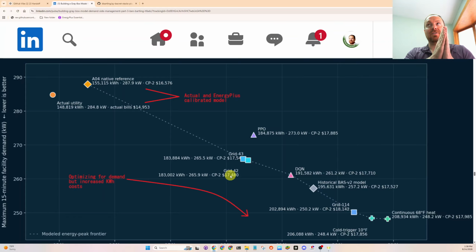do a series of setbacks. So 60-minute pre-start, 180-minute pre-start, even longer than that. And then it also has the ability to experiment with different setback zone temperature set points. And I iterate over and over and over with an EnergyPlus model, a calibrated one, and you can come up with the most optimized way to start the building, still meet zone temperature set point with the most optimized cost for that day based on the actual utility rate tariff. So that was the idea behind this science experiment.